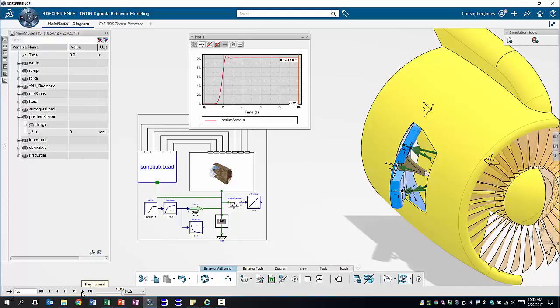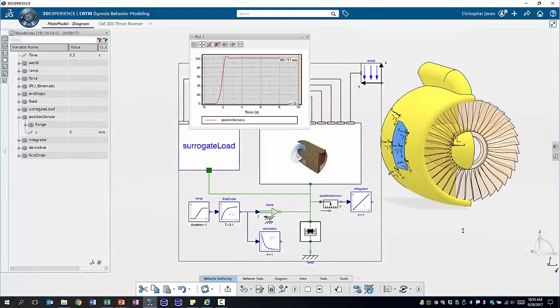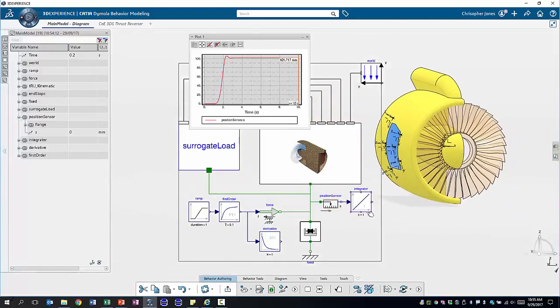Now, rather than trying to manually find an optimum force that we can apply which is high enough to actually open the door in its entirety, but not too high in order to waste energy, we're now going to run parameter optimization using Process Composer. To that end, we need quantities that we want to optimize. And in this case, we want to optimize the integrated signal of the position, so the area underneath this curve, in order to maximize the displacement.